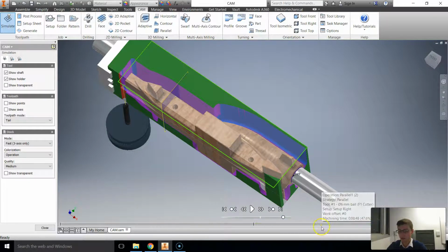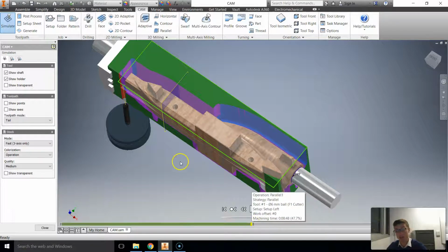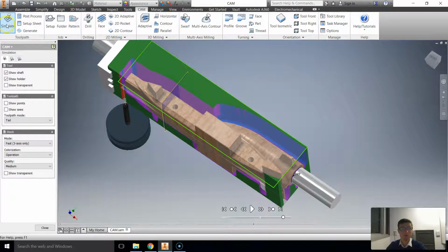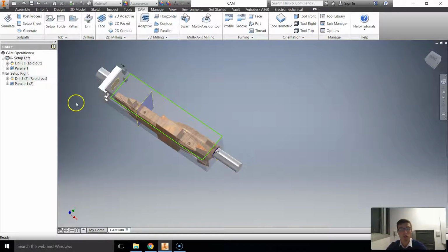You'll notice that if you hover over these green bars, it tells you the machining time roughly of that section. So that's 8 minutes of machining, nearly 9 minutes. Another 9 minutes, let's say 10, plus the extra bits because they're only 18 seconds. It's about 10 minutes per side. Cool. Having done that, that's what I would like to see, personally, looking over your shoulder.